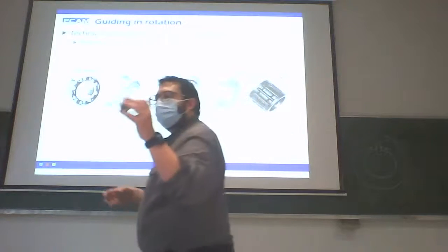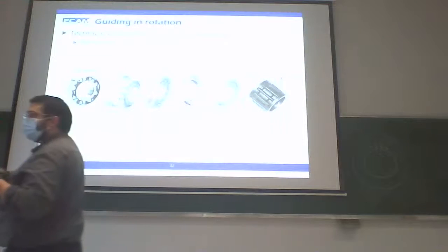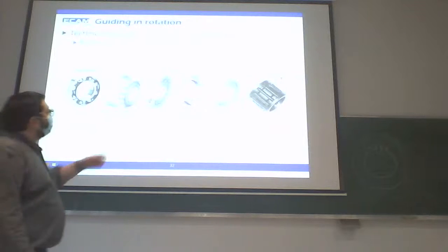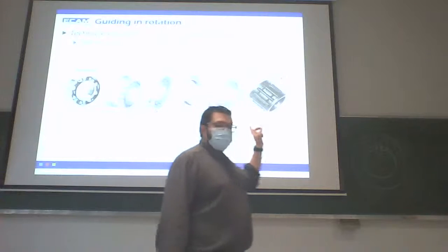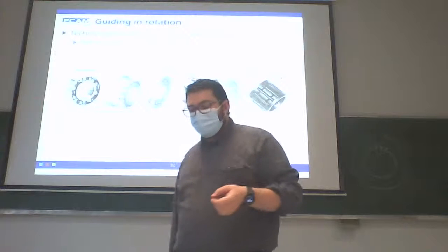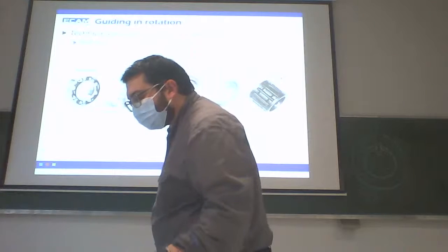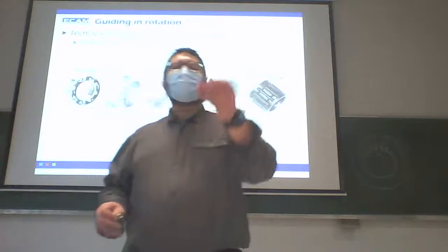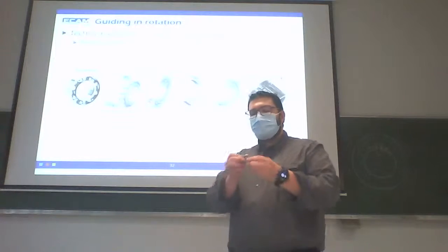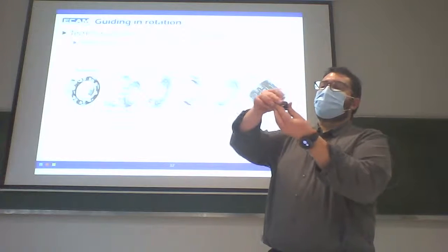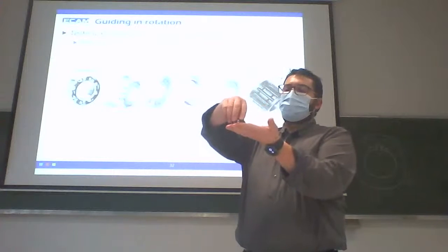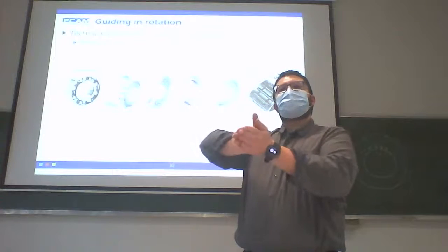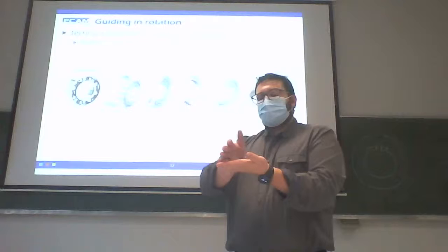Here it's for important axial effort, to stop them. We can find roller bearings with small needles, so very small cylinders. We can find plate bearings. We have balls like this, two rings, and here you have a rotation in this direction. It is used to create a rotation between two plates, for example.